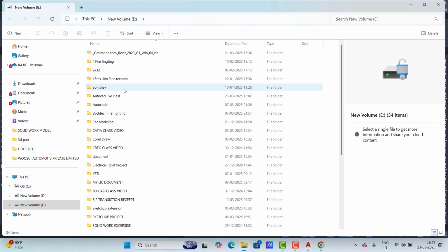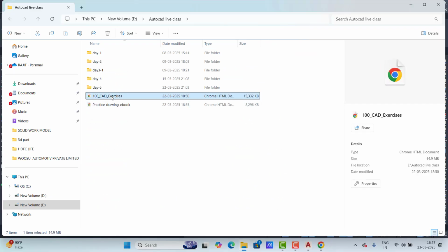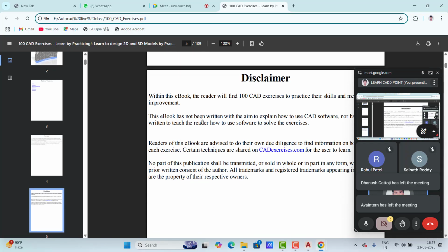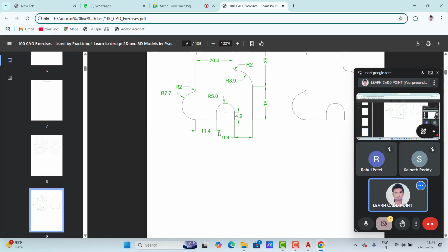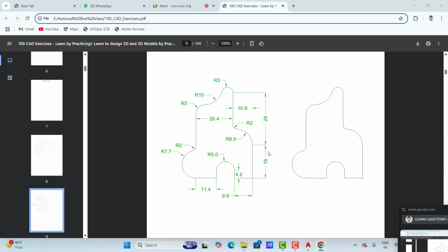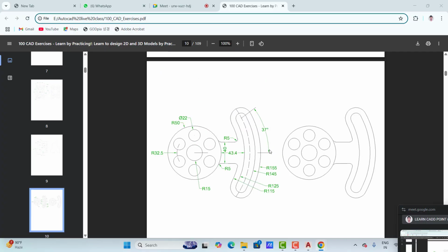Now this arc making, tangent arc making. Tangent arc making means we use the circle, tangent, radius option. So we can use here C enter, T enter. First tangent give, second tangent give, and radius type 100. Enter. So this we created. After that we can print.